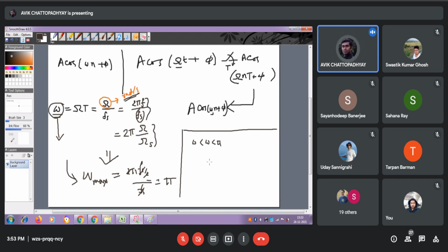So it has basically two spectra, one for the positive half and the other for the negative half, the positive values of the frequency and the negative values of the frequency. Whatever positive frequencies exist, the negative counterpart must also exist. So the spectra exist in both directions. That means this relation can be written such that omega ranges from minus pi to plus pi, or in general 0 to 2 pi.